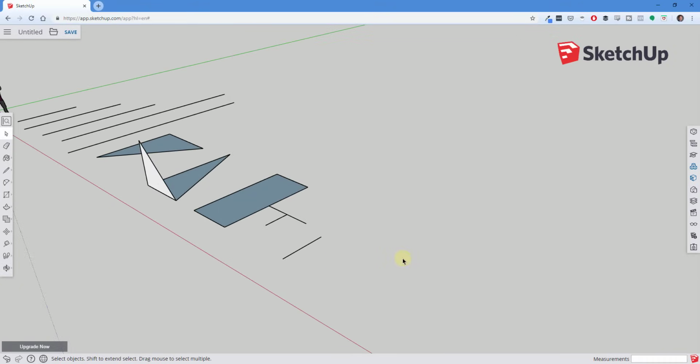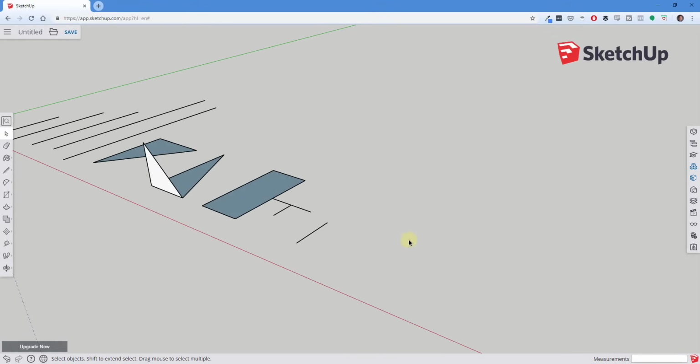And so we can talk more about those in the future, but those give you kind of an idea of what you're drawing along. And the most important one that you need to be aware of is when you have a tool active like the line tool, you need to be most aware of the ones that are indicating that you're drawing along a certain axis. And the reason for that is whenever you're drawing inside of SketchUp, you want to make sure you're drawing along an axis so that you can be sure things are coplanar.